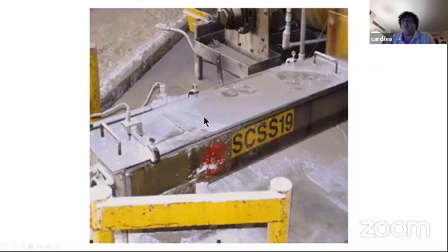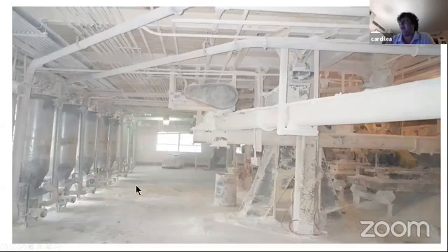See, it looks like a snowstorm hitting here. Basically, it's a huge amount of dust, sugar dust everywhere, powdered sugar, granulated sugar, all kinds of different sizes. As you can see in this picture right here, it's very, very small. There you can see up on these piping, you have a bunch of it piled up. And notice how the picture is cloudy. That's where particle size comes into play because it's all throughout the air there. So this whole area pretty much has an explosive environment.